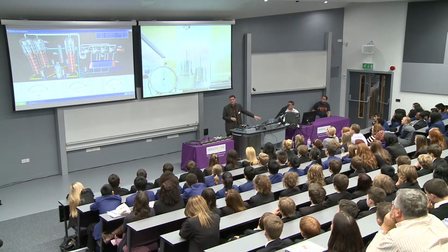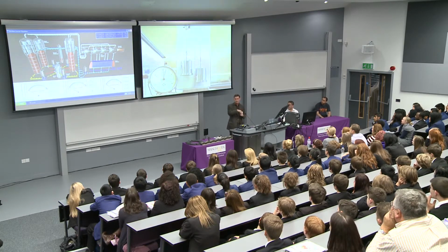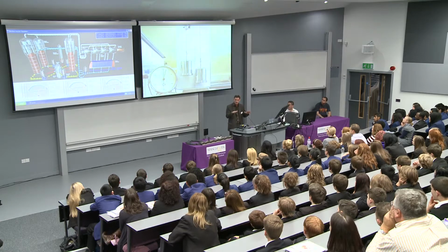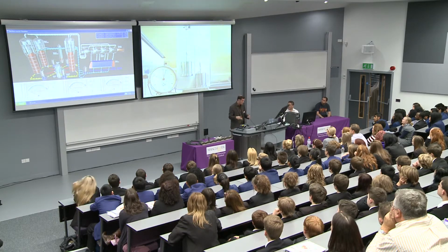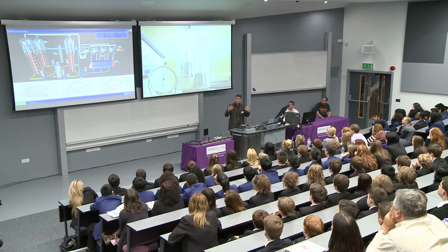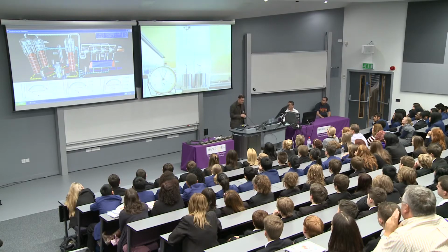The last example is rate, how quickly or slowly things happen. And this is a really important aspect for nuclear power stations. Here you can see some weights on some wire, some lead wire. And you can see slowly the wire gets longer and longer and longer and longer. And that process is actually called creep. Eventually, things break due to that very slow deformation process. And you'll see the one on the left break in a minute. And that's one of the factors that limits the lives of nuclear power stations, and something that we try and control. There we go. Okay, so the materials that we choose for our power stations is incredibly important.